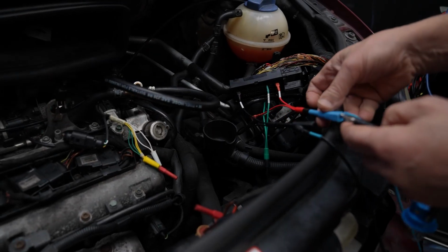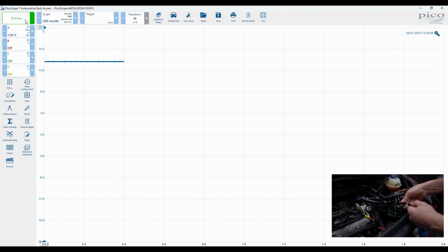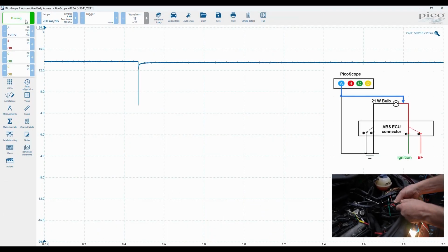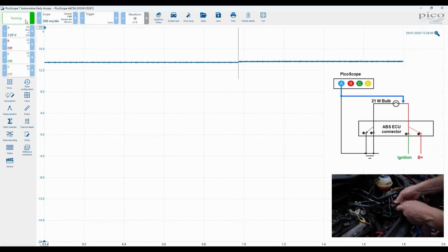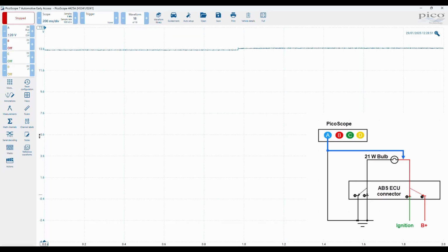All right, so capture the voltage drop on the supply. So we're just looking at voltage at the moment when we apply load. So if we just let the PicoScope run, and at that point there, and then remove and pause PicoScope. Now if we go back through the buffer, we see the precise point where we applied load to the circuit. If I just pull this down and change the scaling slightly.